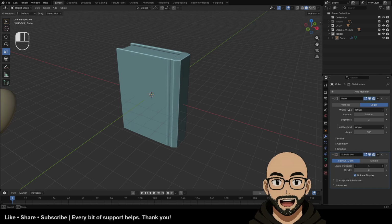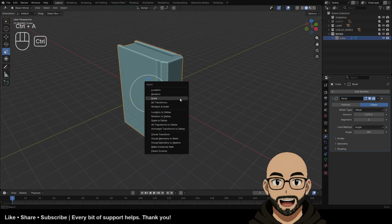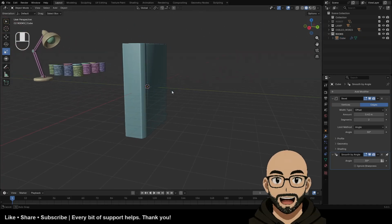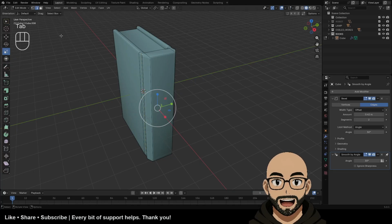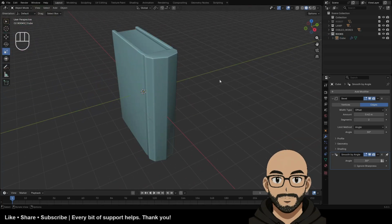And then if you don't want the subdivision, you don't really need it. To be honest, you don't really need it. The bevel's not too bad. We can hit Control A, apply scale, and then we can adjust that bevel a bit more. Shade auto smooth. We have a book. Now, if you want a more curved book, because right now that's very sharp, maybe if I go here, add a cut down the middle, and I can just put this out too. Shade auto smooth.